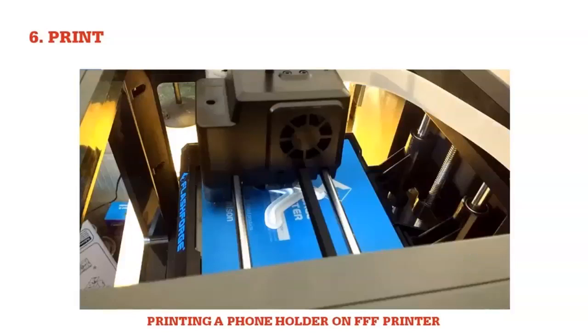If you look from the top view, this is it having printed a few layers. The narrow part in the middle is actually the phone holder on its side, starting to build up some height. The flatter, wider part that's underneath it is what we call the raft. The raft is there to provide a bit of stability to something that's thin and a little bit unstable, and to help us get some adhesion to that print bed. In this printer, the print bed isn't actually heated because we're only using PLA plastic. So we want to get as much adhesion and as much stability as possible, so it's got what we call a raft at the bottom to add it.